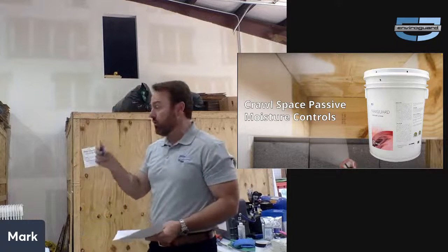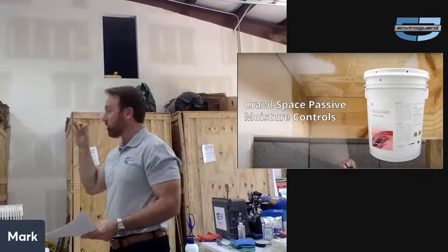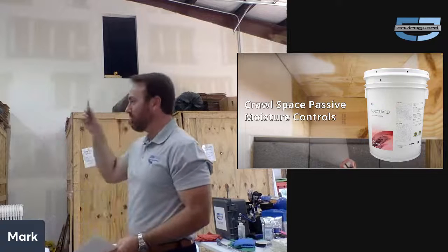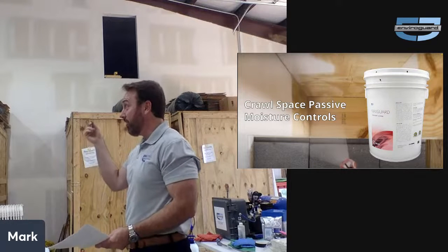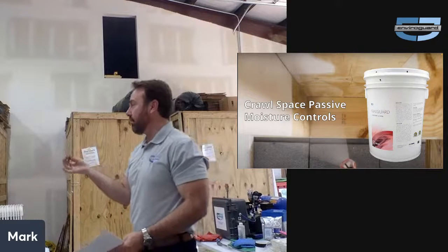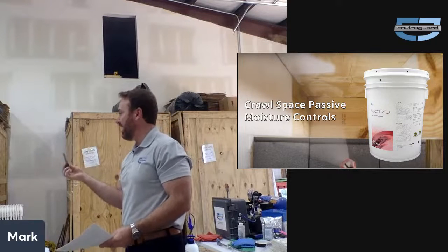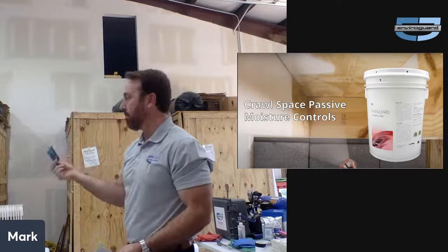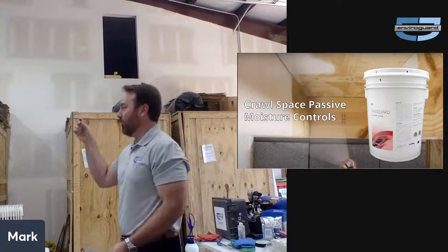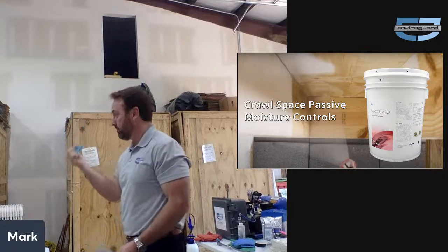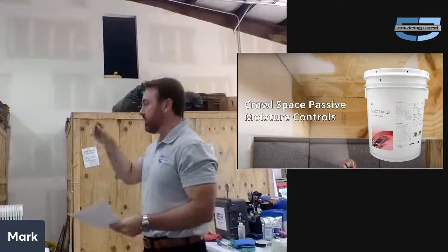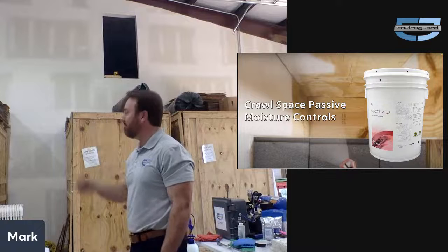So the way that you know two things, what your cost is and are you going to be profitable on it, is based upon your wet mil specification and nothing else. Otherwise, you are just playing Russian roulette with your coating application, and you're happy if you make money, and if you don't, you're like, what happened? What was the problem? This little tool makes you profitable. Okay? But that's only the initial application. Once it cures, right, this is where it matters.